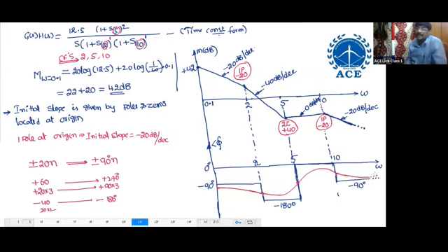Select the midpoints at corner frequencies. Here the midpoint is below, so start below the 90, pass through that, and then go a little bit close to the approximate value. Again, draw it, then it will become the phase plot. It is the approximate shape of the phase plot. So they'll give only approximate plots, and that also only 1% chance for a phase plot. 99% they'll ask only the magnitude plot. If they ask anywhere for a phase plot, proceed with this procedure.